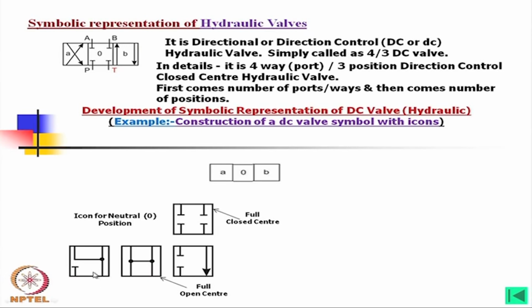The question is: why are we keeping this pump ready, why are we running the pump when the load is not being lifted? Actually, in many cases we need this actuation system very often, that means on and off, the load is being lifted, again coming down, again being lifted, and on that occasion it is better to keep this oil ready for the operation. It is beneficial compared to starting the pump and again lifting the load, which will take more time without much saving of energy. Okay.